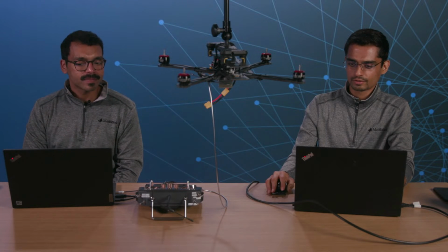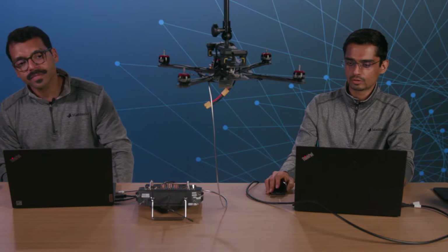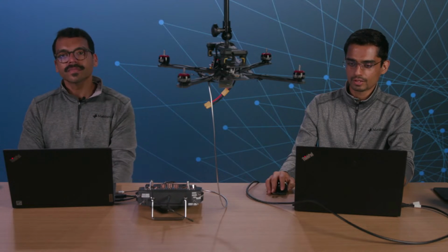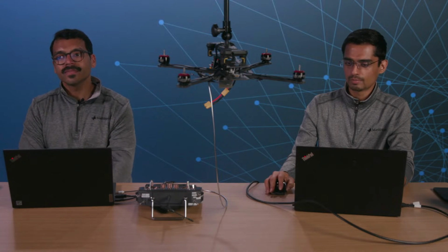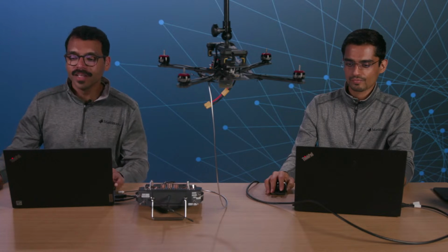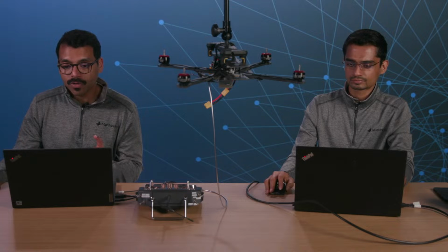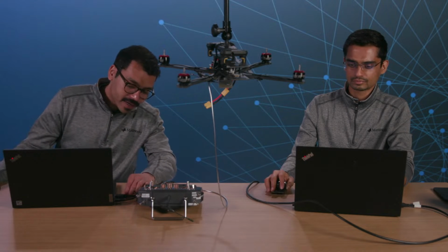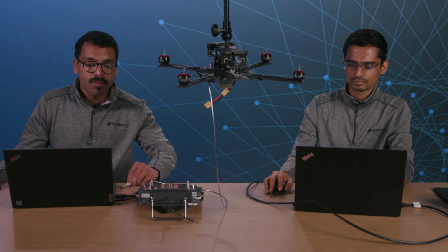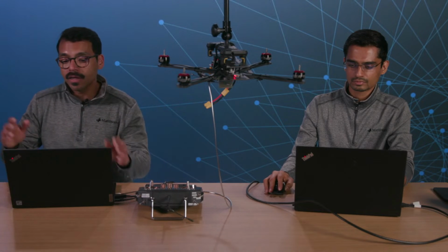Another one here: is there any explicit requirement to select a certain airframe in QGC prior to setup in MATLAB to enable all main and aux PWM output channels? This is a really good question. And yes, there is a requirement that in QGroundControl, when you have your platform connected, you specify what your airframe is, and what kind of aux channels you are going to send data to.